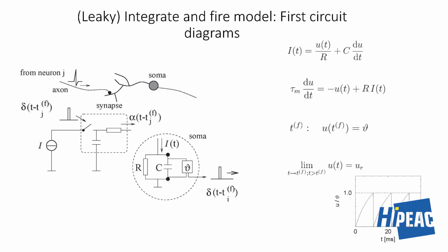So people have seen we can easily build these neurons, just with a couple things, maybe a couple more. I'll show you a couple more that I needed. And then we need to do this magic with the threshold and spiking. But for threshold, we just need some comparator. You hardware guys know better than me how to build a comparator. And then if threshold is reached, we'll do some magic. We'll probably discharge this capacitor that has accumulated all that potential, and we'll start the whole story again.